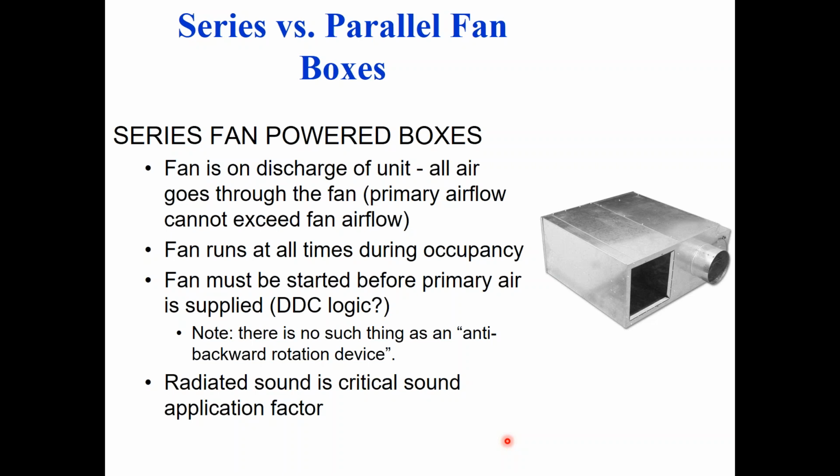So the fan is on the discharge side of the unit, and I'll show you the inside guts in a minute. All of the air for the zone, every CFM that comes into that zone, has to go through that fan. That's why it's in series. When we get to the parallel one in a minute, that won't be true.